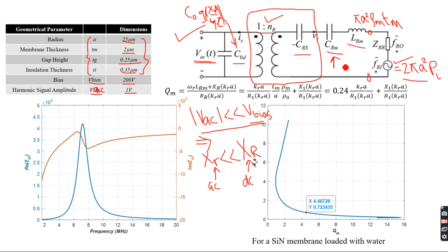It is the inverse of the Hooke's constant. It can be represented in terms of the Young's modulus of elasticity of the material, which in this case is silicon nitride. If I remember correctly, this is 9 (1 minus sigma square) a square divided by 80 pi Y naught, where Y naught is the Young's modulus, and then T_m cube. T_m is the membrane thickness, and if you have a thicker membrane, then you have a smaller capacitance. It's less compliant. The compliance capacitance decreases.